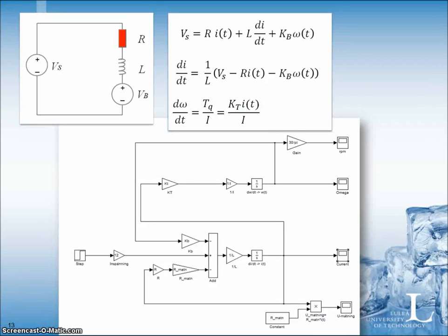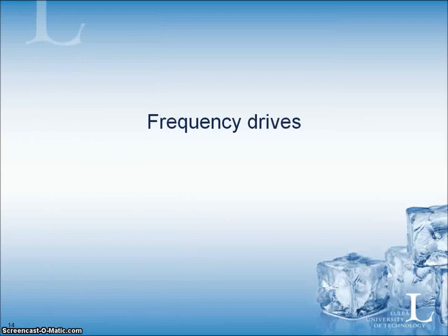And this is something you should think about, because in the startup sequence, or if you have a machine that is going very slowly, you will have this high current and normally no cooling, because the fan is connected to the shaft of the motor, and that might give you problems with the windings and the brushes. So follow the instructions on YouTube and let's move on to frequency drives.